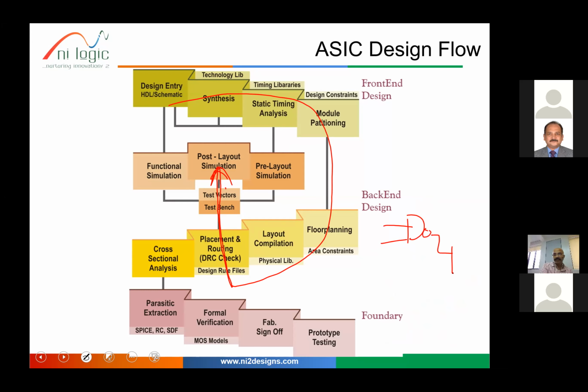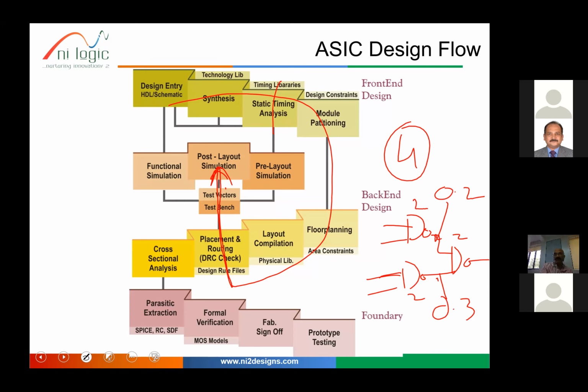Because as you are using a gate design like this, after the layout, here the delays were like this. Okay. So the total delay was earlier coming 4 after the STA. Okay. But after the routing, the delays of these interconnect wires in between might also play a role. This might be like 0.2 and this might be 0.3, something like this. So now the delay of this side is 4.3. So this is the slowest path, B to Y.